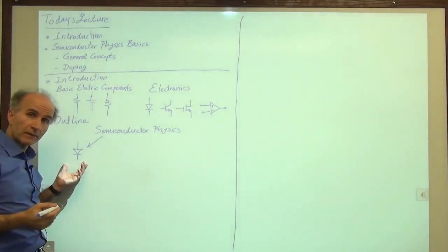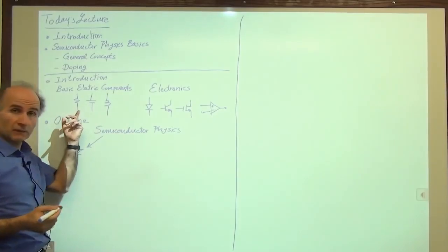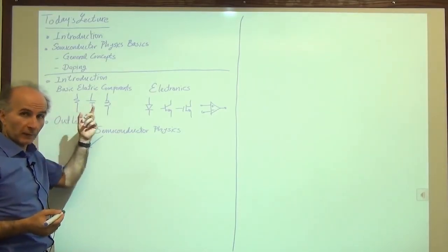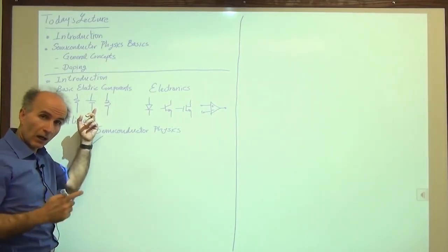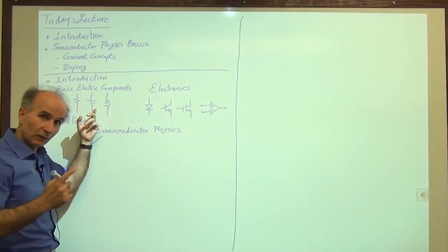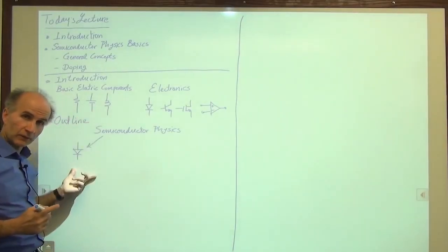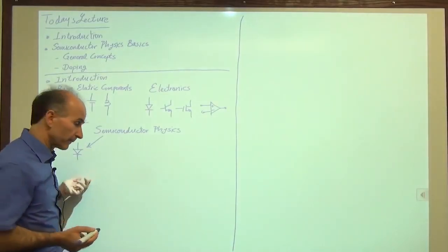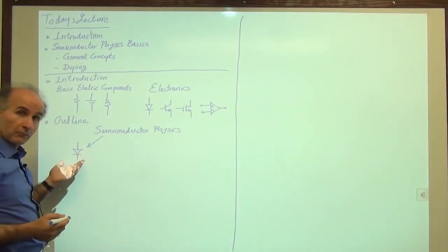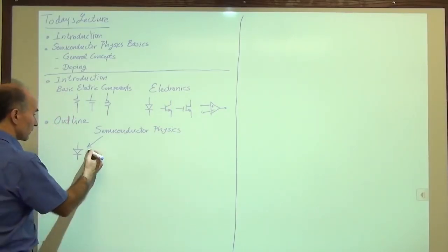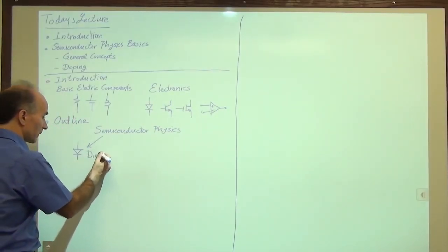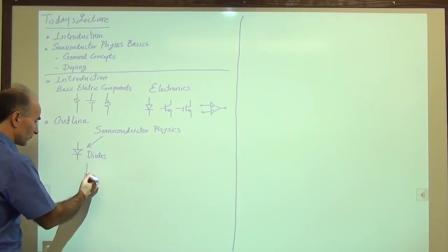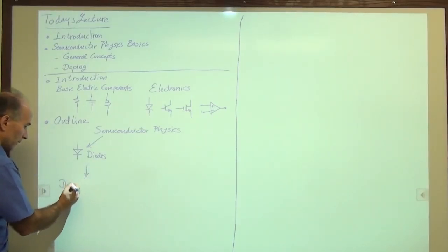can model this. We remember that a resistor satisfies Ohm's law. We remember that a capacitor satisfies I is equal to C dV over dt. How about a diode? What model, what mathematical expression should be used for the diode? And once we know that, we can go and build circuits out of diodes. So we learn about diodes, and then we go to diode circuits.